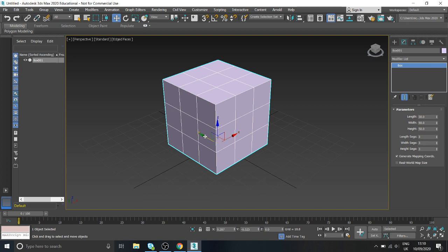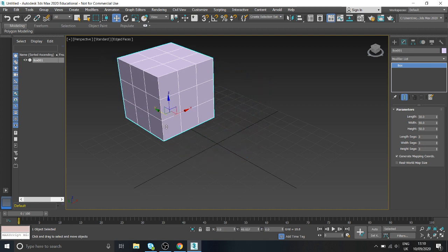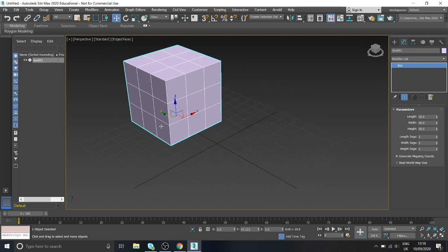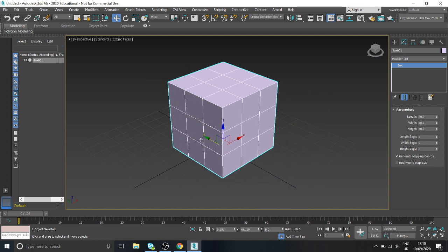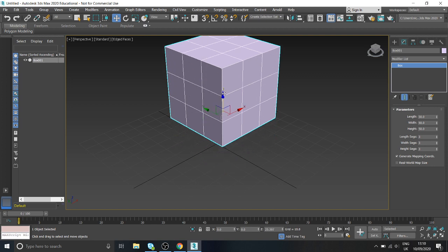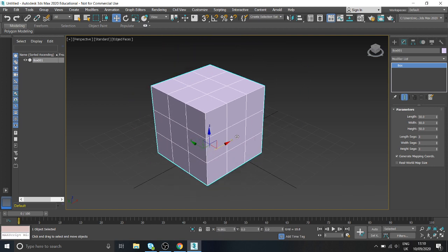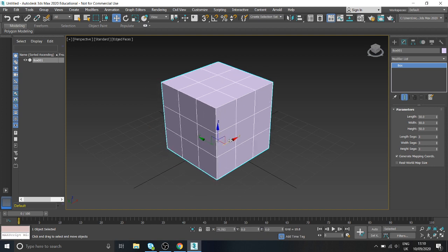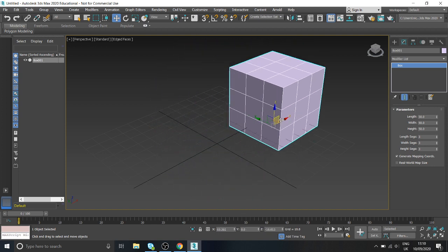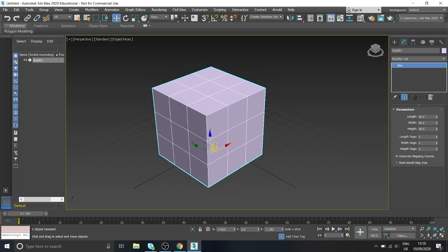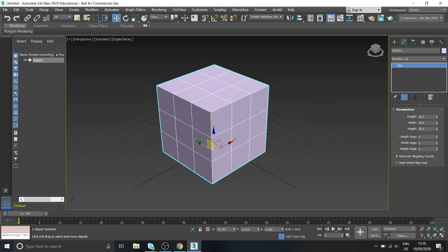So if I just want to move something constrained in that Y-axis, you need to make sure when you first select it that just that is selected. The same with Z, it will only move up and down, and then X, it will only move back and forth that way. But if I did select both of them, it will move in both directions, which you don't always want. So be careful when you are moving and rotating and scaling things that you use the gizmo correctly.